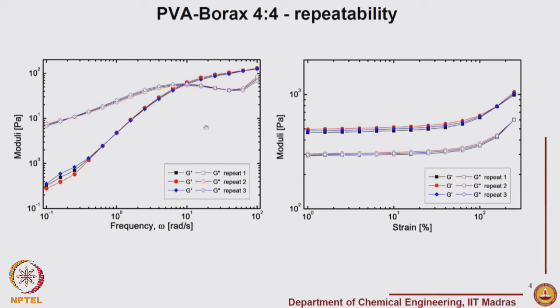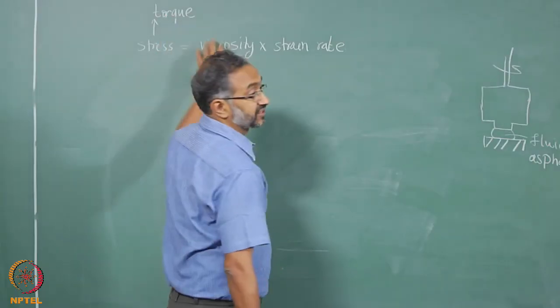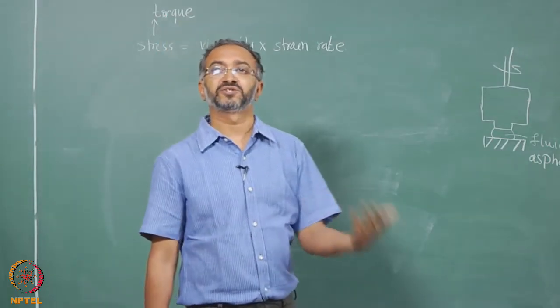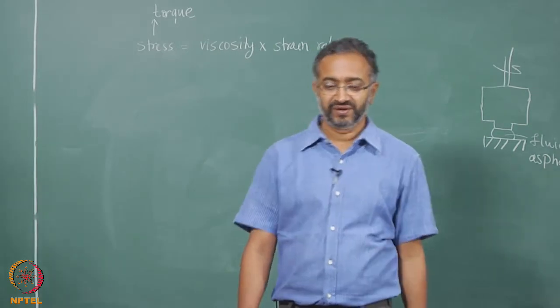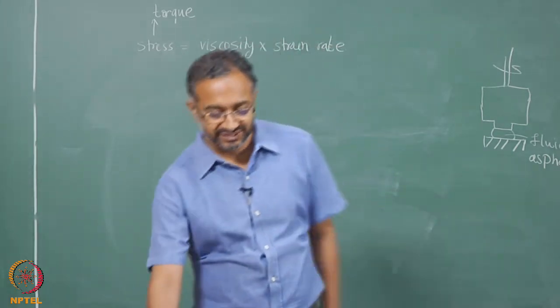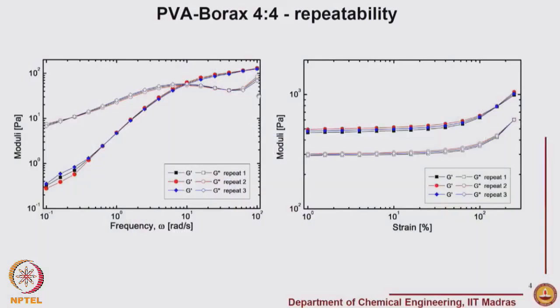Another important thing from a rheometer point of view is that at low frequencies is where the issue may be, because when you have very low frequencies you have less torque, and therefore instrument sensitivity is a problem. In class we have also discussed that at high frequencies sometimes you may encounter problems, and these would be the other effects, which we have termed inertial effects.